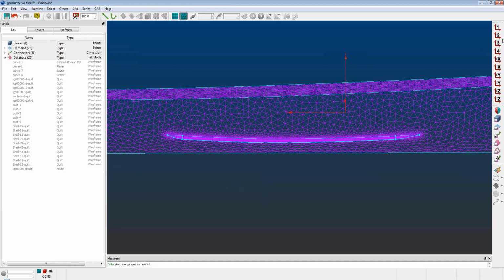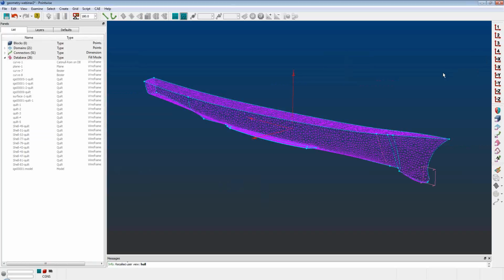Okay, so we're finished. So just a final recap. There are two general approaches to meshing in Pointwise. Fault-tolerant meshing: don't touch the sloppy CAD, fix the errors on the mesh level. Solid meshing: heal the sloppy CAD so meshes are automatically watertight. And remember, these methods are not mutually exclusive. You choose how and where you want to use them to best suit your needs.